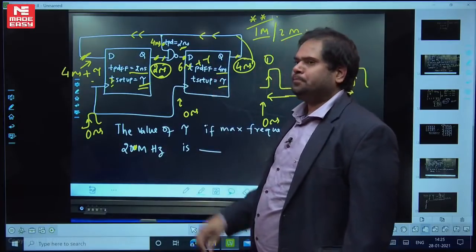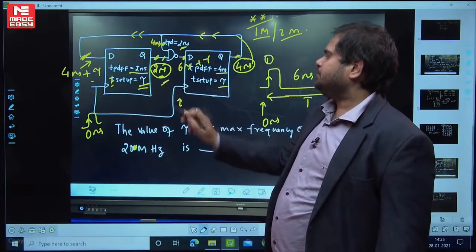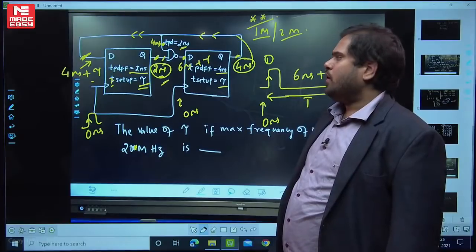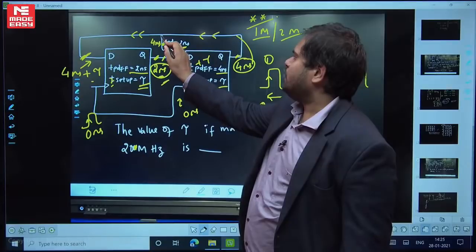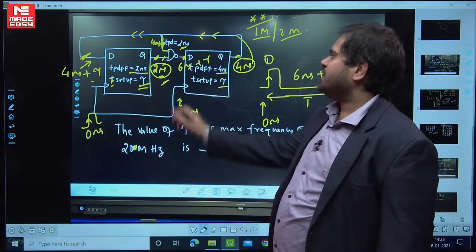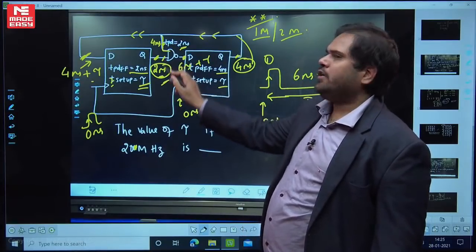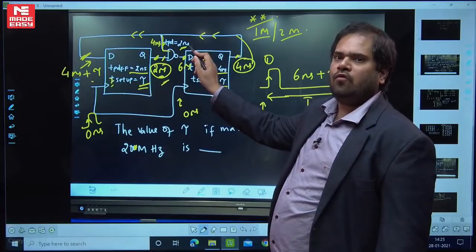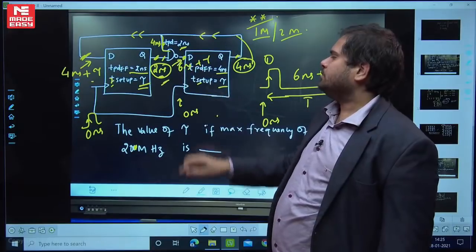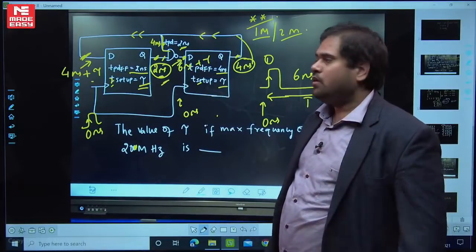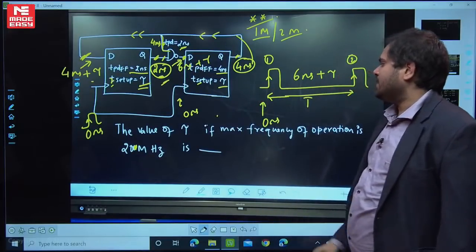इस पे आइए. This is coming at 2. ठीक है? Now when can I apply here is the question. But this 4 is also getting applied here, so this is coming at 4. So we have to take the maximum value, 4. This is taking 2 more, 4 plus 2 is 6. So 6 nanoseconds is the time where this value is coming. But I have to wait for tau again. So 6 nanoseconds plus tau is nothing but my T.